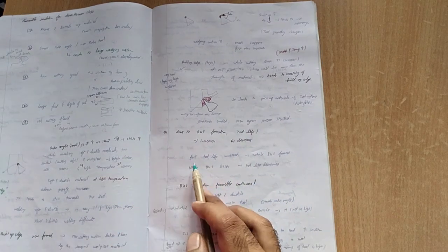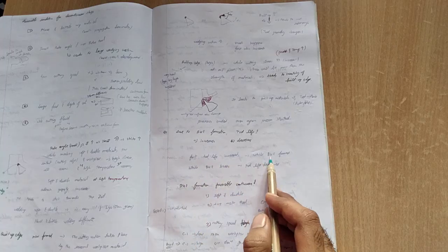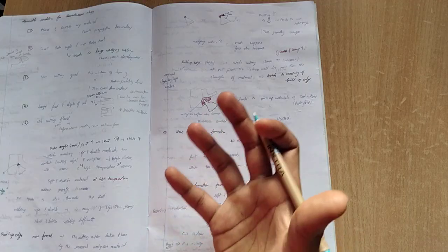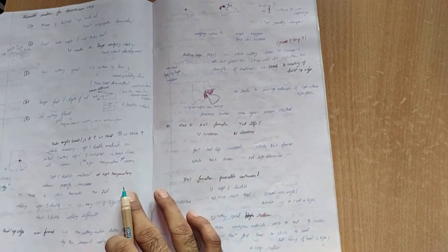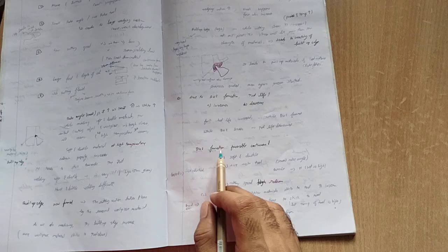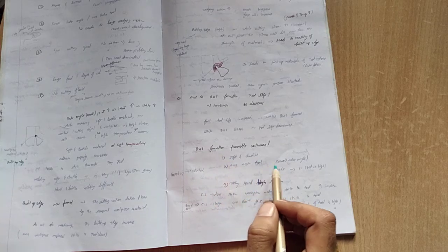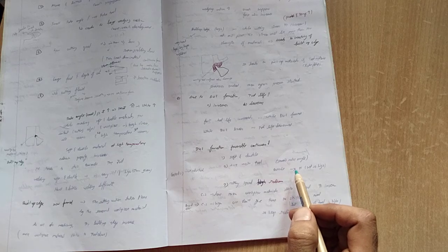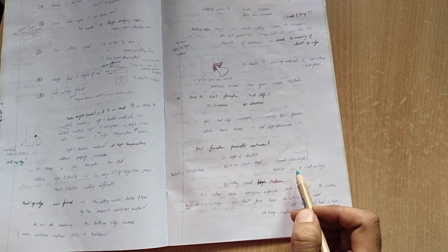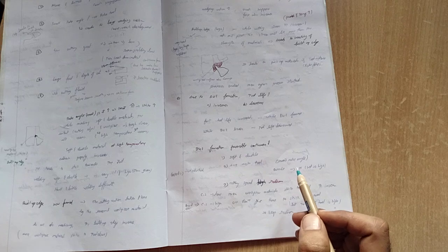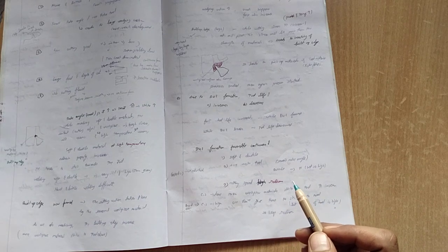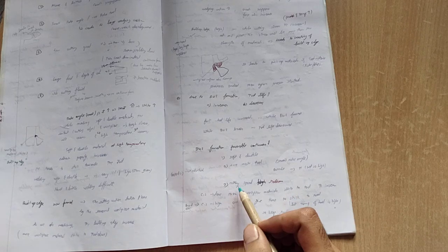At first the tool life increases, because while the built-up edge is formed it withstands a lot of stress, but later on the tool life decreases. So to avoid built-up formation, there should be a positive rake angle for soft and ductile material, a smaller rake angle otherwise, and the cutting speed must be medium.